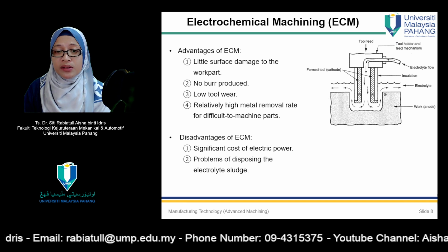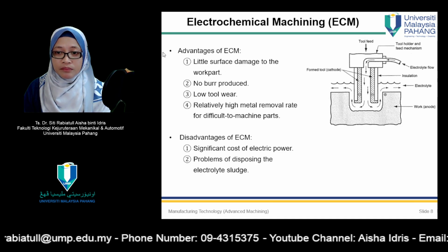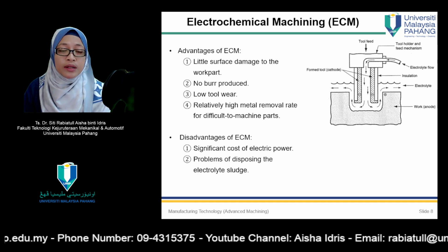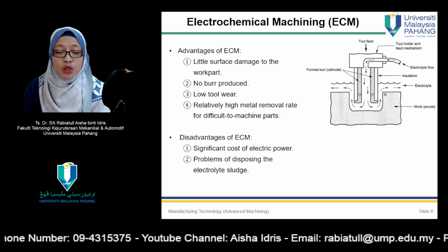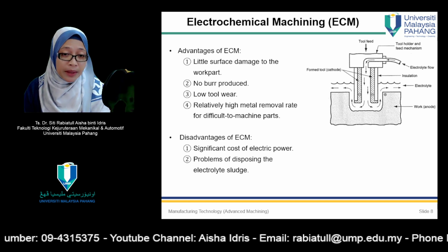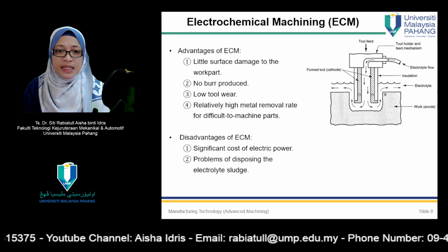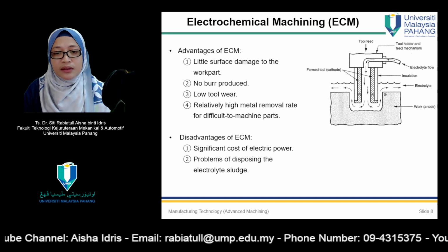Electrochemical machining is generally used in applications in which the work metal is hard or difficult to machine, or the work geometry is difficult to accomplish by conventional machining methods. Work hardness makes no difference in ECM because the metal removal is not mechanical.